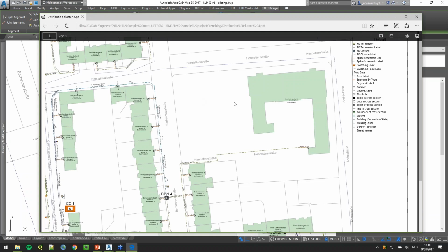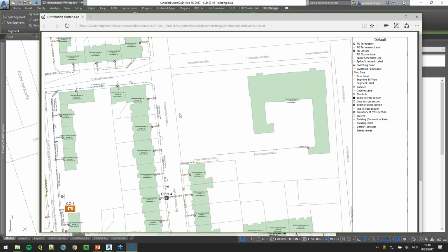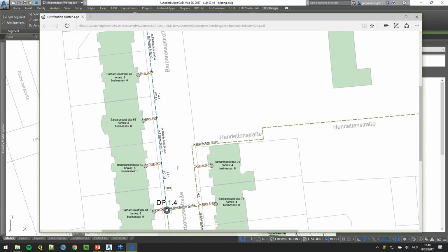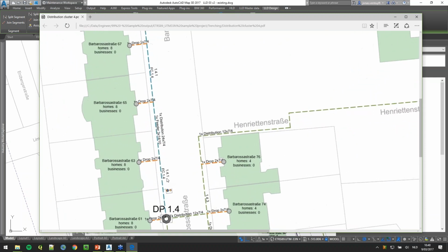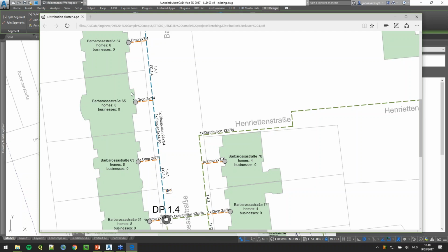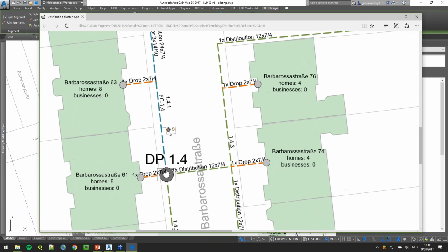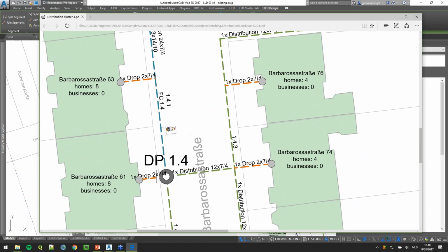And then also another map, so you can style the plots the way you want. You can indicate which information needs to be visualized. For the permits, we just had the trenching locations. In this case, we have a lot more detailed information, where we can see the drop cable that needs to be deployed. You can see a section here of how the microducts are being utilized in this segment.